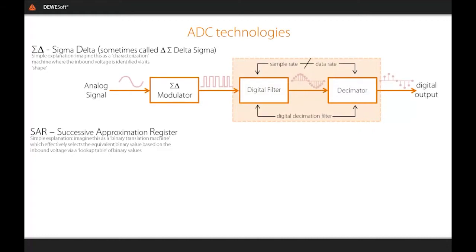It is really a single bit that is overclocked, although you shouldn't relate that phrase to what you may have done to your home games computer. It has almost nothing in common. The overclock is really the sample clock. It is the bit that tells the ADC when to take a sample. In a Sigma Delta, it is typically at least twice, and that's good old Nyquist there, what you really want. And oftentimes it can be many tens or even thousands of times faster than what you actually see being available to you for recording.